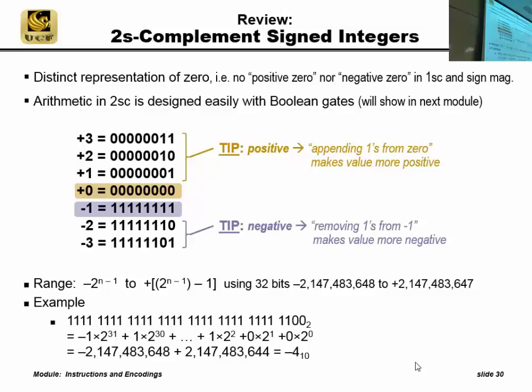Then what? The first one is 1. 1 tells us it's negative. You can see this is going to keep going. How many ones do I have to subtract before that most significant one goes away? A whole bunch, right? So the way to remember it is the most significant bit, if it's a signed representation, it turns out it's 1's complement, 2's complement, and sign of magnitude, which we'll show you, has the property, if the most significant bit is a 1, it's a negative number.